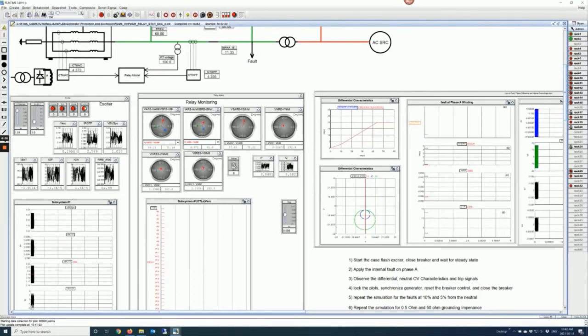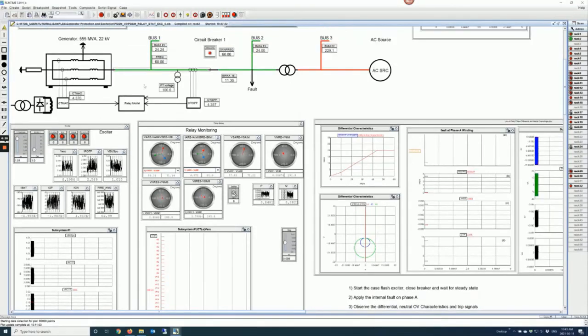Once you lose excitation on a synchronous machine, on the rotor side, the stator tries to compensate for the loss of field on the rotor, and that draws more current on the stator. It's abnormal operation of the machine, and to detect that, there is one method called the Mho element. Basically you look at the terminal, at the voltages and currents. Impedance seen from that terminal changes, and you can detect that through that impedance measurement. If you look at the vector of current, they're going to increase.